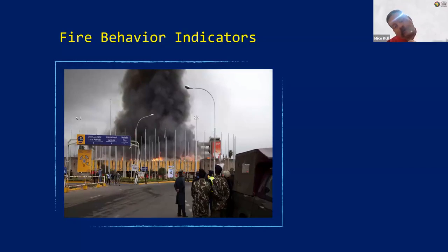Wherever that fire is pushing all of that heat and smoke out of the building, that's the exhaust flow path, right? And by looking at where the air is going into the building and where the fire and smoke is exiting the building is going to give us an indication of how that fire may travel through the building. All right, so that's called our flow path.